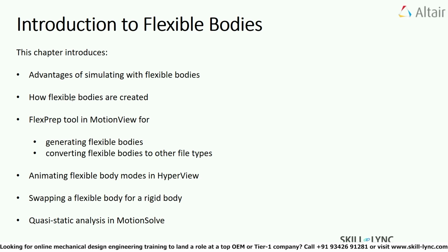Next, I will show you how we can create flexible bodies in MotionView MotionSolve. It is very easy in this software to create the flex bodies when compared to other software tools, since it has a built-in FlexPrep utility which makes it very user-friendly. The FlexPrep tool in MotionView can be used for generating the flexible bodies and also for converting the flexible bodies to other file types. I will illustrate both applications of the FlexPrep utility in this demo video.